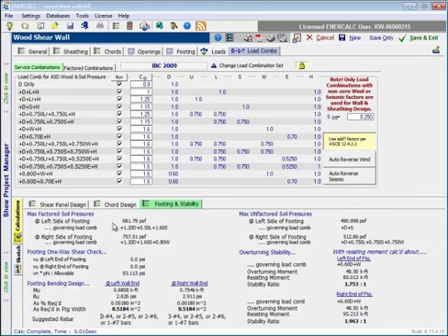At the left side of the footing and at the right hand side of the footing, in units of PSF, along with their respective governing load combinations, the load combinations that produced these pressures. Now these are factored soil pressures, so not something that you'd want to use necessarily to compare to an allowable in a geotechnical report, but instead they're reported for reference because these are the values that are being used to drive the force that ultimately is creating the design loads for reinforced concrete design.